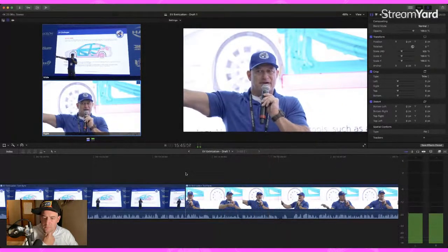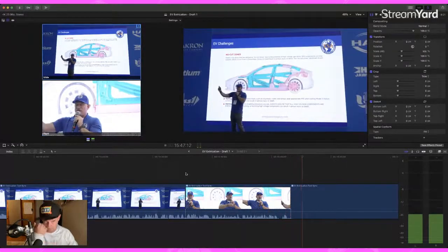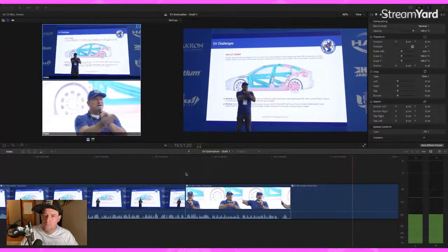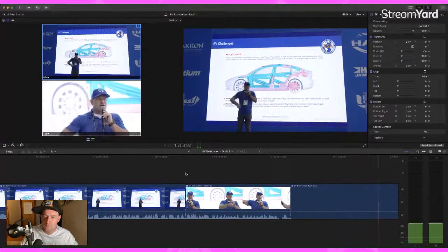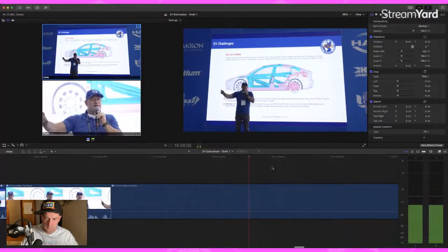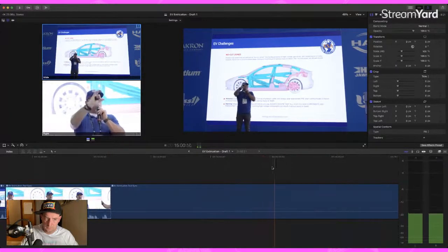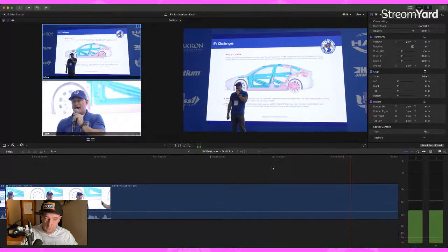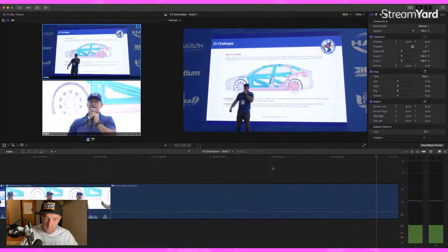Okay? Watch your floor pan movements. All the newer vehicles, the traction battery packs pretty much encompass the entire floor pan, right? So if I do any of my traditional load movements with rams or spreaders on the rockers or the floor pans, if you tweak the floor pan or the rocker panel and you apply pressure, there is a good probability you're going to be applying mechanical damage to your batteries, all right?